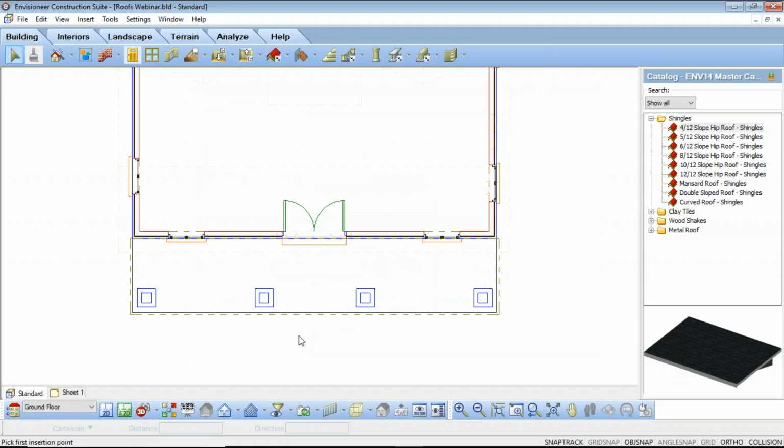And the next thing I want to talk about is creating a different type of roof feature, kind of like a little gable end over top of our roof here. So when I select this edge, we can see that there's only one arrow here. And if I was to convert this to be a gable, it would just make this a flat roof here, and it wouldn't create the gable end that I'm looking for. So what I need to do is take advantage of a tool called break. And I'm going to use the two columns here to act as my breaking point for this roof.